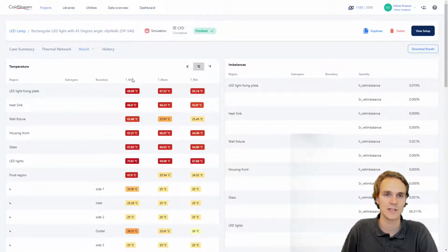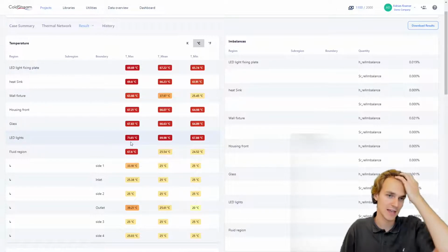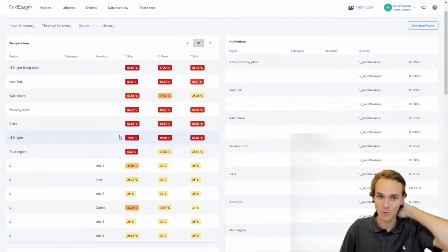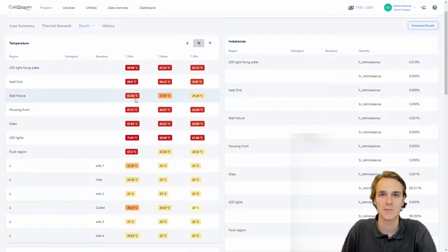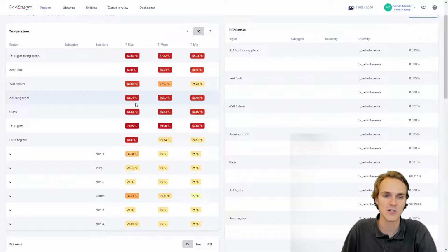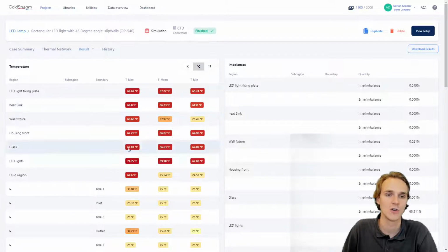So here, for example, you have the Tmax, Tmean, and Tmin. Again, seeing the Tmax, actually at the LED light, it's 71.65, but again, it's staying underneath that 100 degrees C threshold. So we actually proved what we wanted to showcase, and that is that given the operating condition, what are my temperatures? Am I staying within the allowable range? Which was the case here.